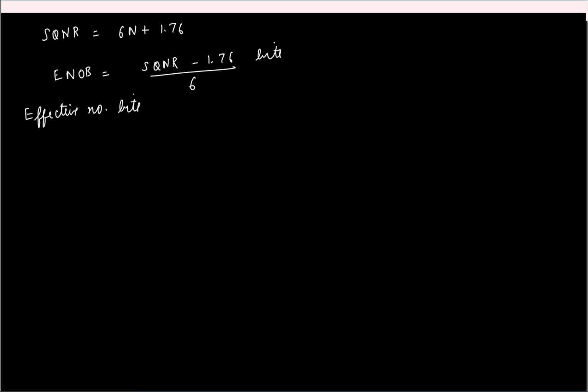We need to have this measure because, for all that matters, I can take a 4-bit ADC, add some 3 random digital bits, connect them to ones or zeros randomly, put it in a box, say I have 7 digital outputs, it's a 7-bit ADC, and sell it to you. But that's not the case. Just because I have n digital bits coming out of my ADC, it doesn't mean it can effectively quantize to that much resolution.